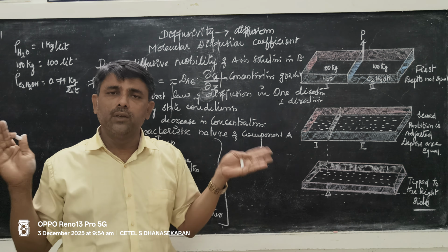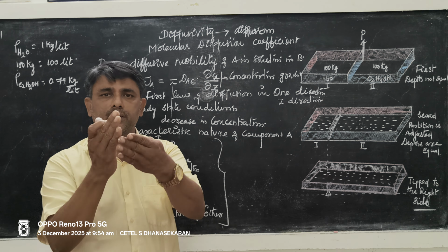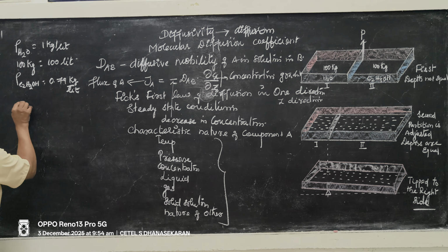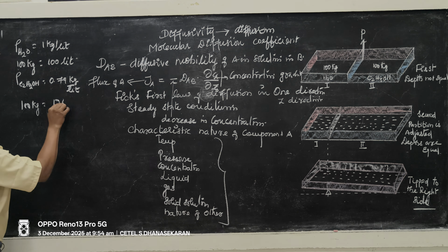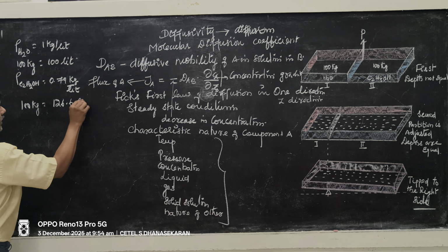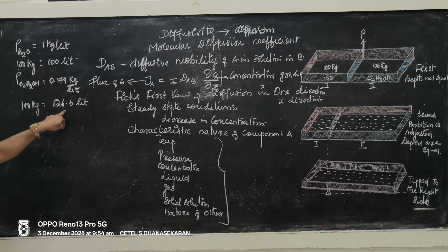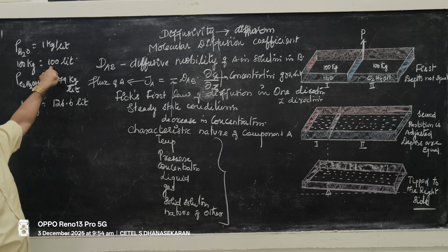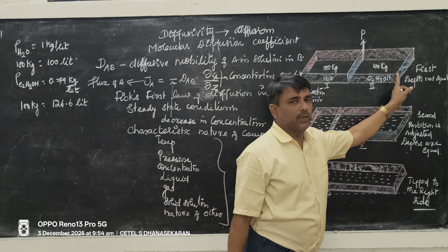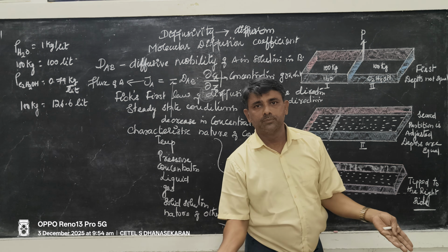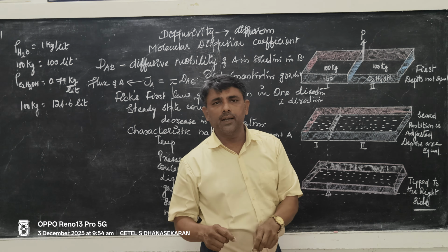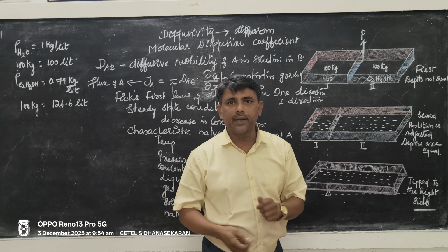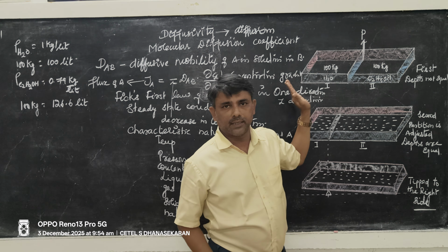If you are taking 100 kg of ethanol, its volume becomes 126.6 liter. So volume of ethanol is more than the volume of water. Hence, the depth of the liquid will not be same. In order to provide the equal depth on both sides, the partition is adjusted towards left.